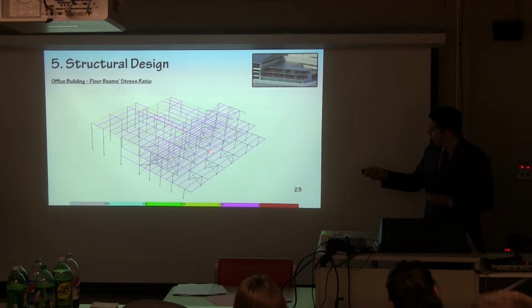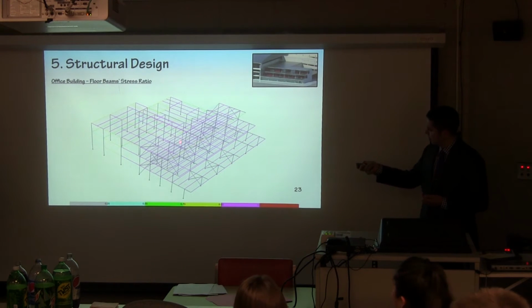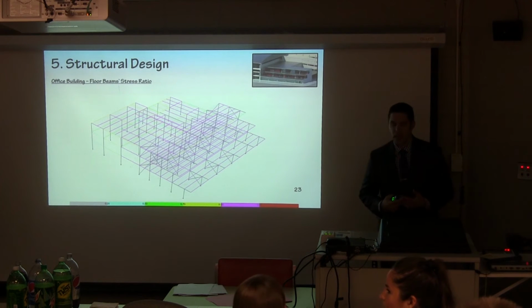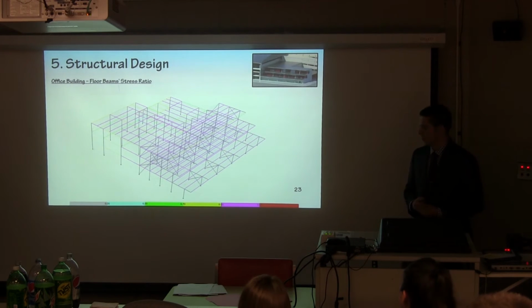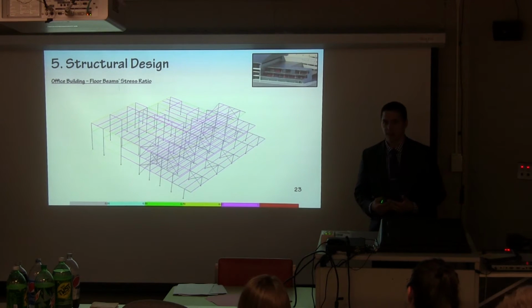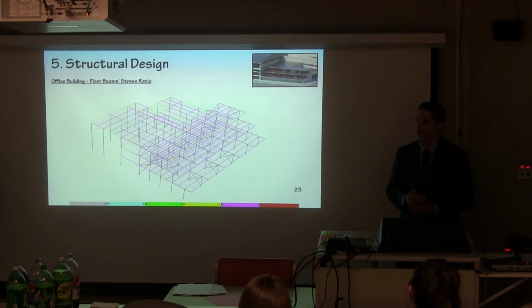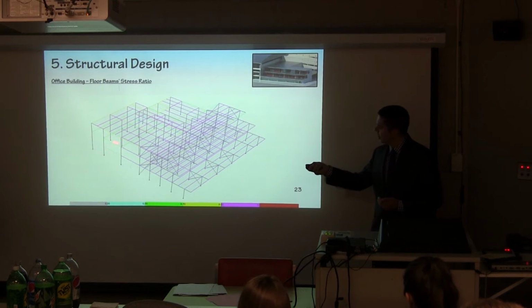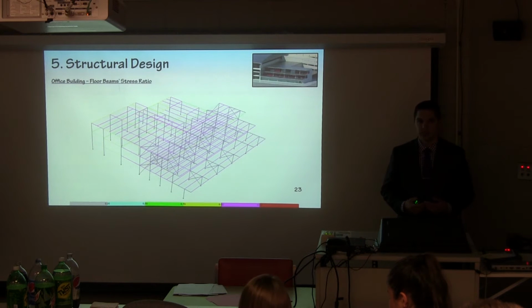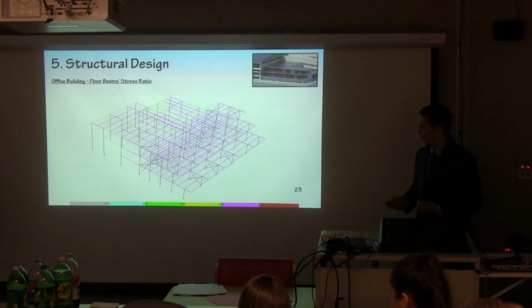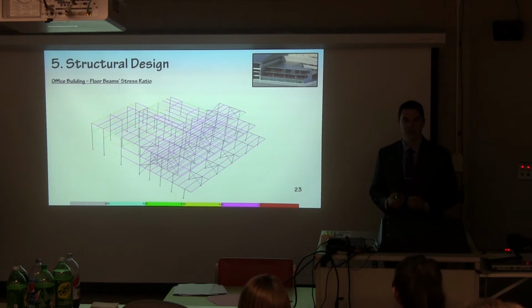And then here we have 6 cantilevers, and the problem with those was they kept failing. They were originally a W18 by 35, so in order to fix that, we had to increase them to a W21 by 68 and a W24 by 68. Another area here is the same thing I just talked about with the last part of this building: serviceability is controlling, and therefore the stress ratio is much less.